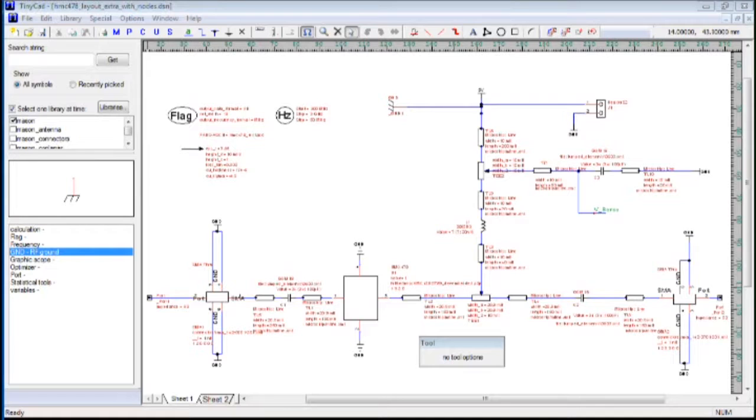Not much of one, but there's a little bit of a change. So let me rerun Mason, and we should see this jump a little bit. Yeah, so right around here you can see a little bit of a change. Again, because we have such a good bias network, you don't notice it that much, but there's definitely a point of actually putting the RF ground correctly there.